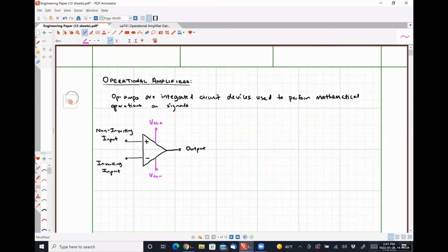Now, when I say for this class, they're effectively optional, in our analysis, they won't show up literally at all. When we do a lab using these components on Friday, if you don't remember to connect the power to these terminals, your circuit won't behave correctly, okay? So for our analysis, we're not going to see these guys again, but for our practical use of op amps, they're very, very important.